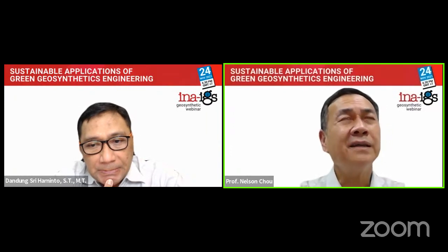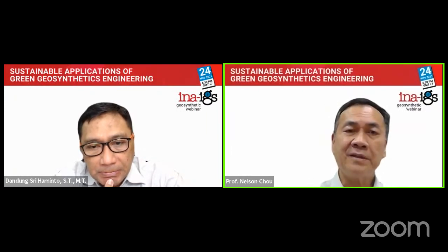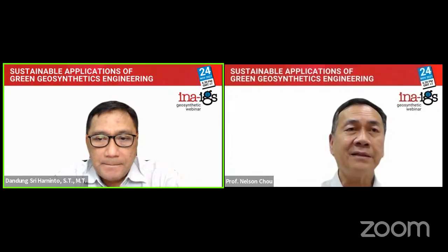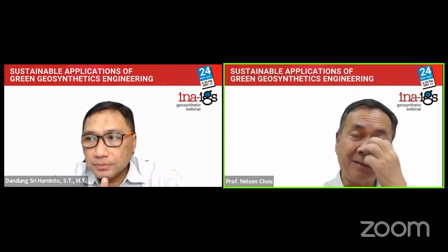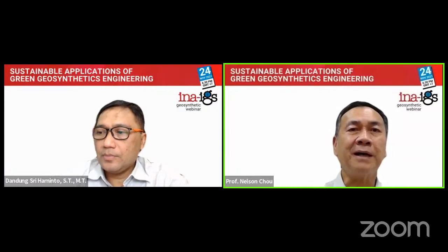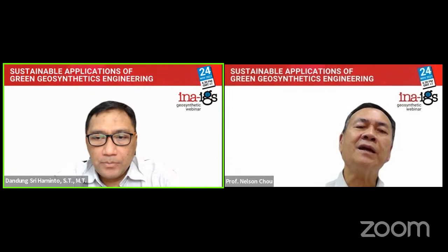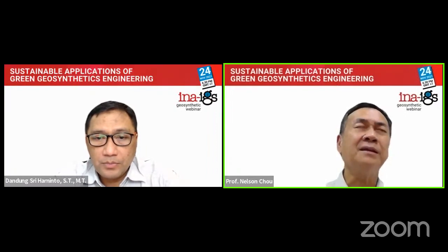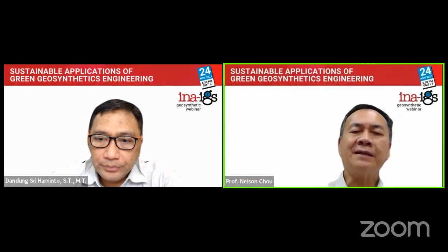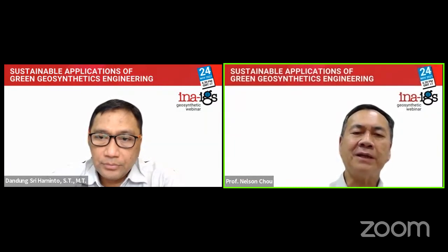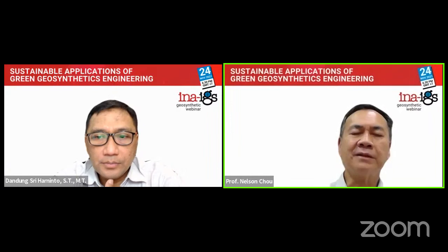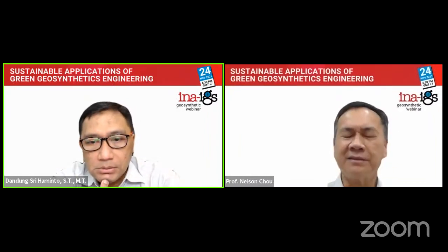Actually, I think I showed a picture. Professor Lee built the geofabric wall along the seashore, and you see the bottom has some holes. Then the settlement did occur close to the bottom. But due to the anchorage, the geosynthetic becomes level after several days. So even though there is some settlement, by using this geosynthetic material, the differential settlement can be leveled out. It's not that critical.